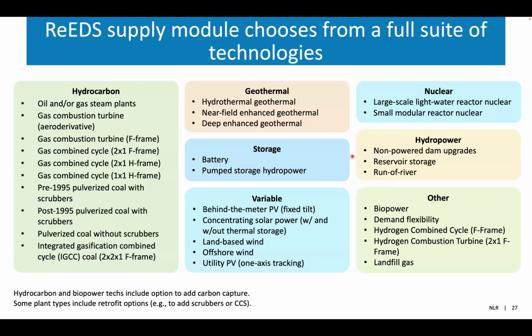Speaking of hydropower, ReEDS can also simulate a variety of different hydropower generating technologies, including run-of-river and powered reservoir-based configurations, as well as have the capability to upgrade non-powered dams. And of course, ReEDS also represents a host of technologies that operate on variable resource availability, including single-axis tracking, utility-scale photovoltaics, fixed tilt behind-the-meter PV, concentrated solar power, and on and offshore wind technologies.